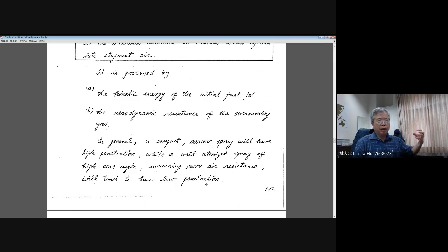You use large droplets initially, and we wish they have a longer penetration, but at the main combustion region, they will automatically break up into so many tiny droplets by micro explosion. Then the advantages of both considerations are reached together for your application in the heating process.